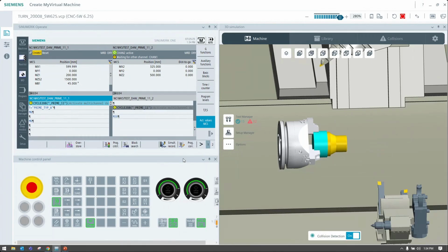So I am curious. I know they always say you got to do the arc in, but what do you think is unique about this insert and the insert geometry that really requires us to do the arcing? Any idea? I know I'm putting you on the spot here, and you're not a cutting tool guy, but I am curious. Well, I don't know specifically what it has to do with the insert. I can just tell you from felt experience, if you don't arc in, it is catastrophic failure.